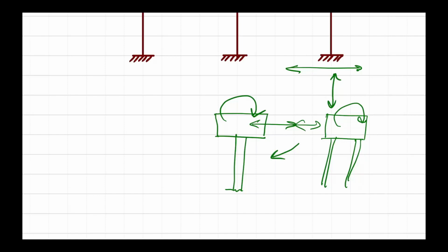So a size smaller than 26 cannot be driven down because it's going to buckle before it gets driven down. But the load, actually maybe I-18 is capable of carrying that axial load. The problem is about the insulation and so on and so forth. So you have to use the pile, and only one pile is more than enough.